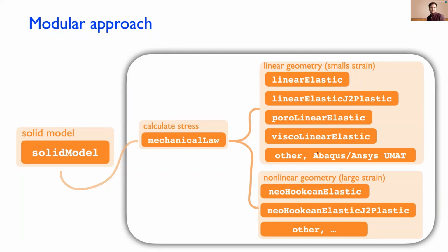And also, can Solids4foam work with anisotropic structures like composites? So there are anisotropic constitutive laws available. So you would specify the material orientations or directions. One thing with composites, because I have some experience working with composites myself, there are many different approaches to modeling composites. So let's say if you're at the macro scale, if you just want to capture the principal directions of your laminates without caring about the plies, then yeah, that's probably fine with some of the available tools.